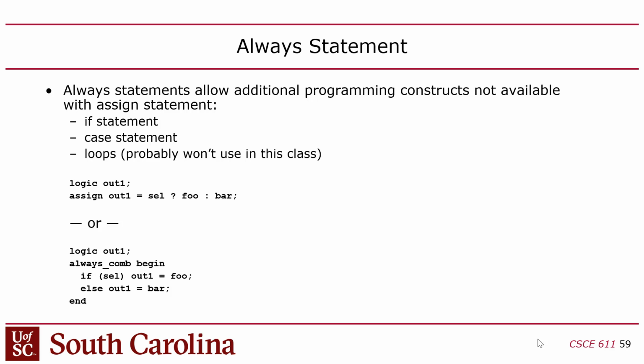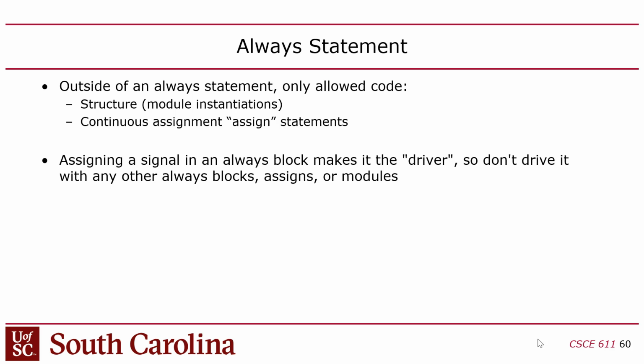So to use a multi-line conditional if statement, would you need to put begin after that parenthesis and end after the line? Yes, exactly. And by the way, you'll notice when you start doing that, it's awkward, especially if you have an if then else, because you have to type if condition begin statement end, then else begin, right? So it becomes a little cumbersome to have to spell out begin and end. But yeah, that's a good question. I didn't put the begin there because obviously there's just one statement in the if and the else.